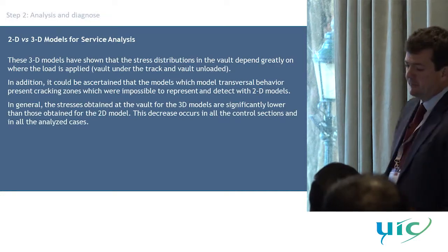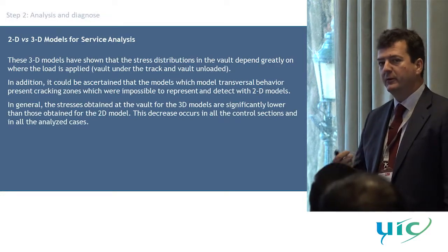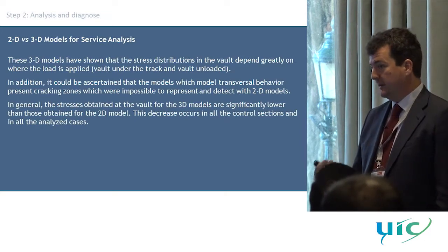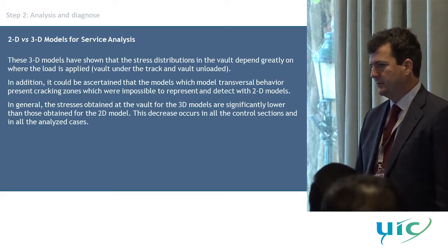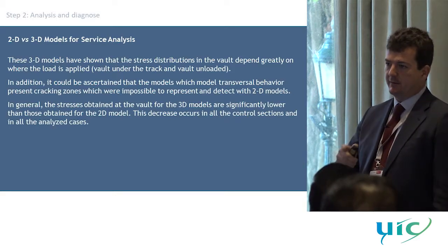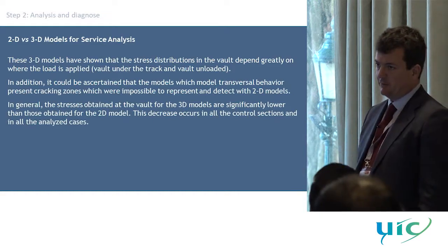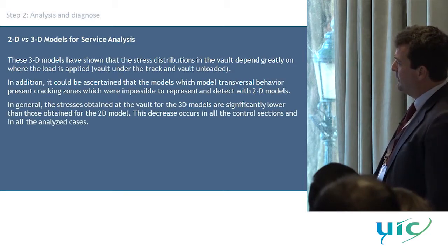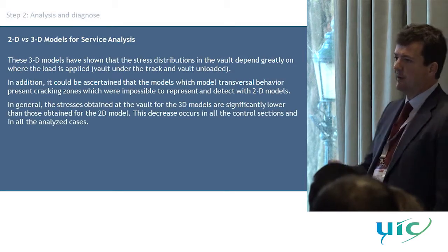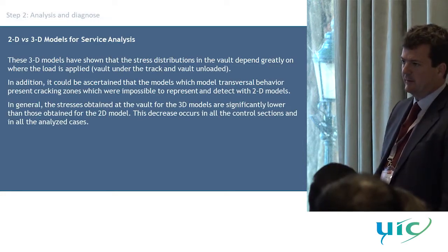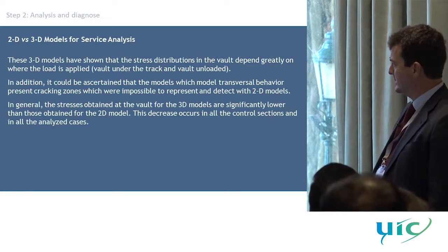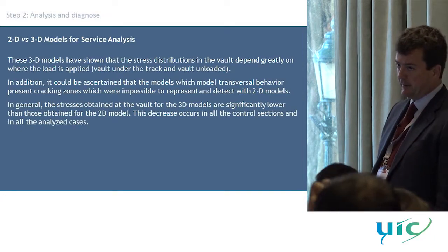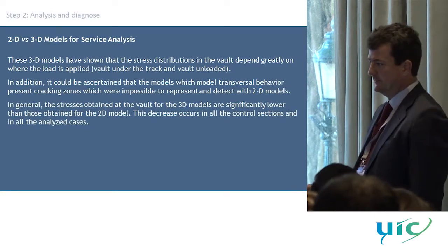And of course, if you do 3D analysis and you are looking for defects, you can model other types of defects that you cannot do in a 2D analysis, of course. And this is true, especially the crack in the vault, not the transversal one, the longitudinal one. You have to be very, very careful. But if you are going for a 3D analysis, you have to have a lot of data. That's the other point that Niam told us yesterday. It's not fair to do very complicated models if the data is not reliable.